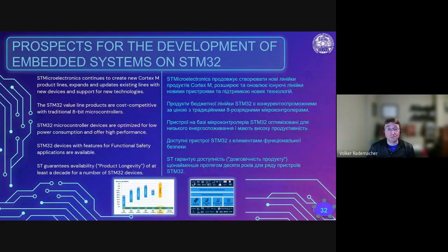USB is complicated. The fine details of USB are complicated. I dare to say, for a microcontroller with an Ethernet interface, it is easier to implement TCP/IP than USB. But luckily, many manufacturers offer libraries for USB support.